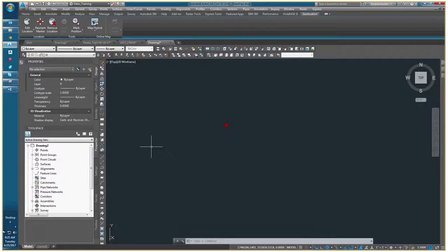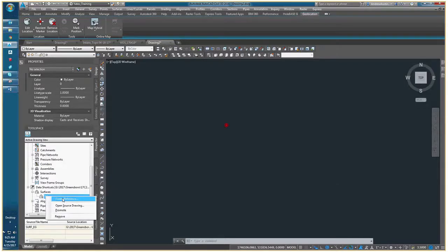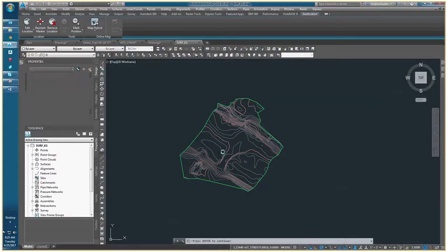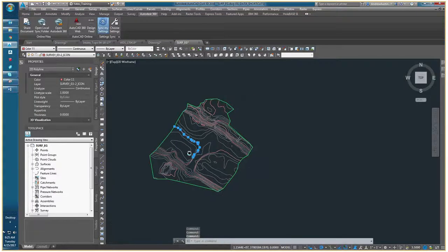Did you delete out the polyline surface? Or are they still in that? The question here from Corey was if I deleted out the contours for that surface, you're asking for the contour polylines? He'd asked if we deleted out the contours for that surface, and the answer is no. The way I'm going to answer it is actually go back into that surface and show you. So these contours are actually part of the definition of that surface.